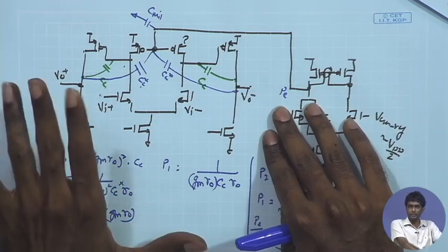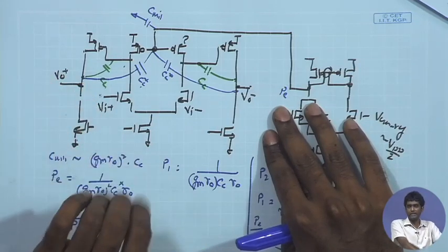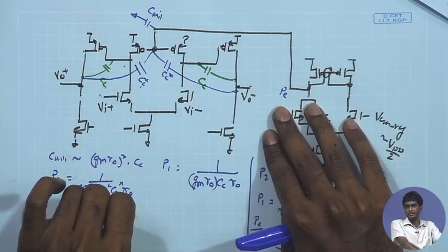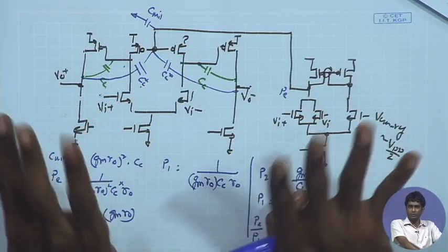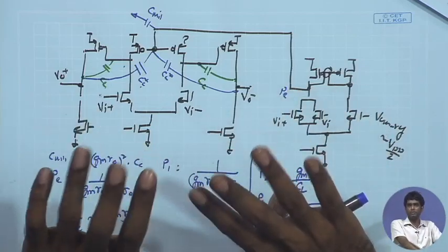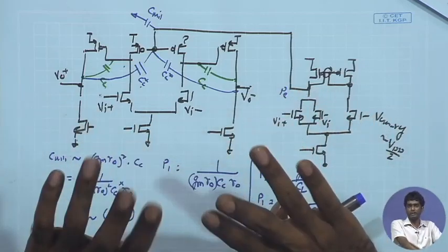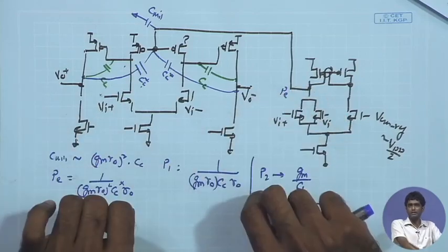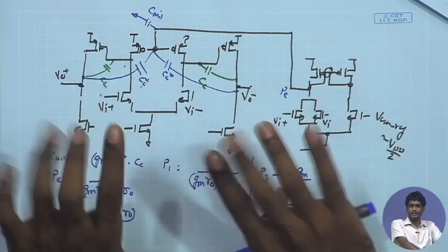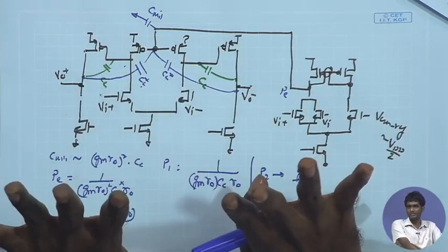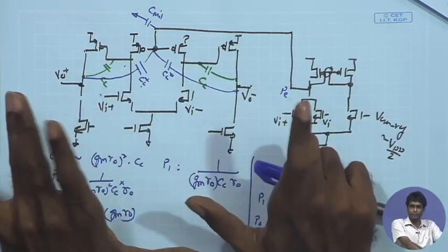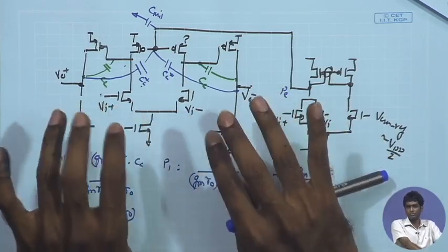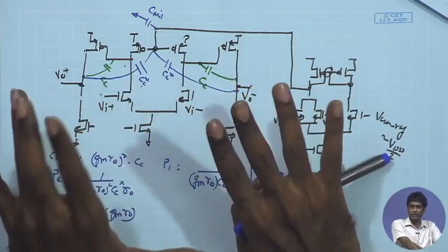Scale technology may give you advantages in terms of noise, in terms of the fT of the devices, but in order to maintain overall integrity of the analog signal, in order to get a better ro, or in order to get a good input referred noise, good stability and compensation, we are seeing that ultimately we are forced to use longer channel lengths for these devices, and therefore the second order model is good enough for most of the analysis or most of the hand calculation you will be doing to arrive at the required sizes.